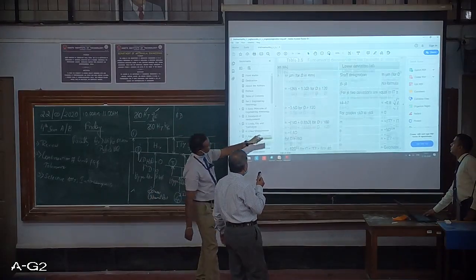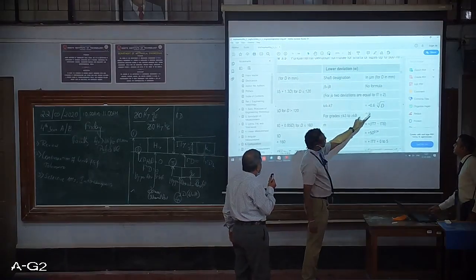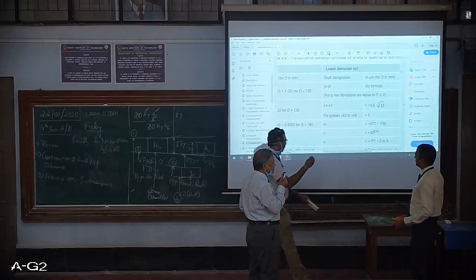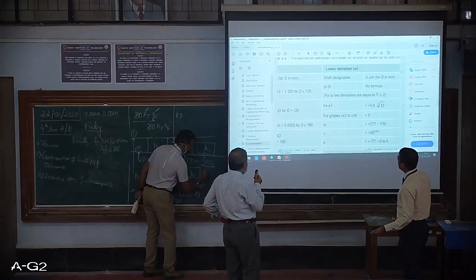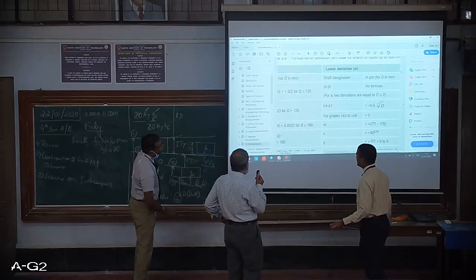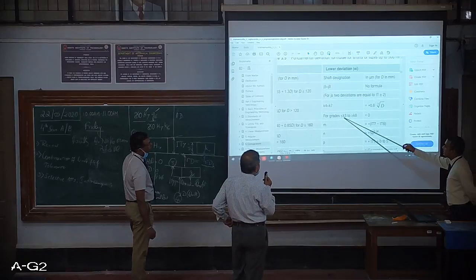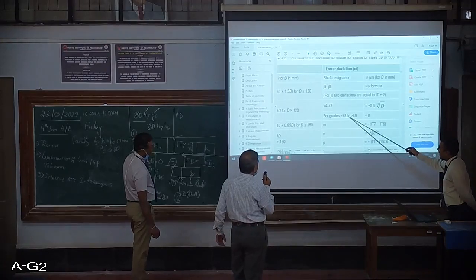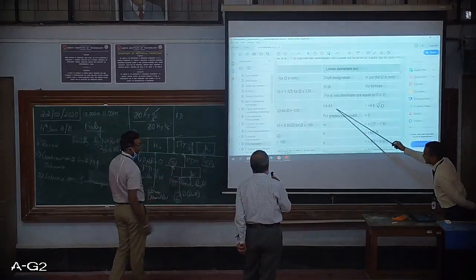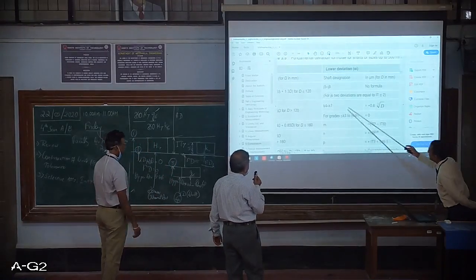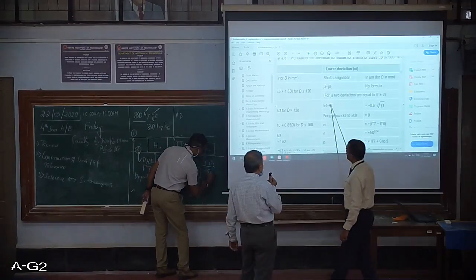For the K shaft, the fundamental deviation is plus 0.6 times the cube root of D. So we can always get the fundamental deviation. There is a special case for K for grades less than 3, where it is 0, a very minimal value. For K4 to K7, it is 0.6 times the cube root of D. So our particular problem falls under K6.